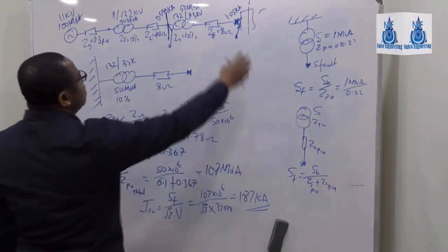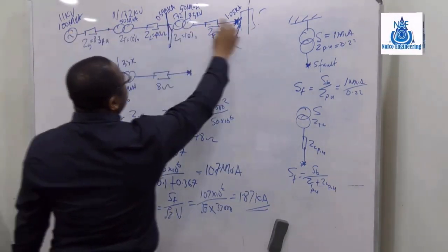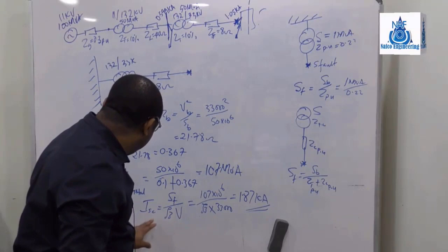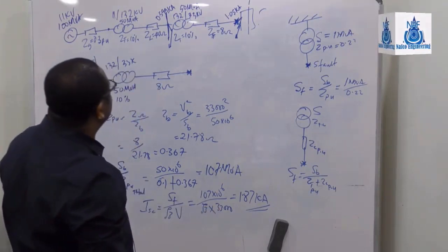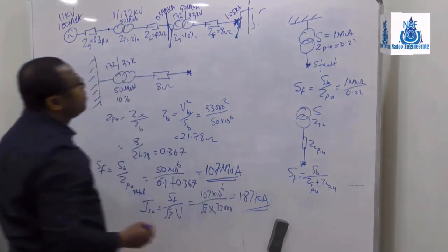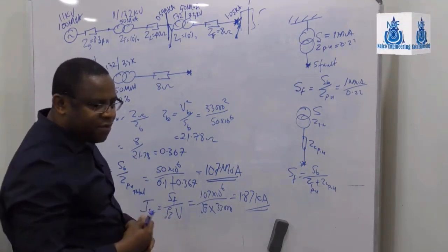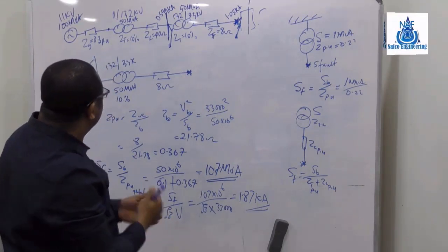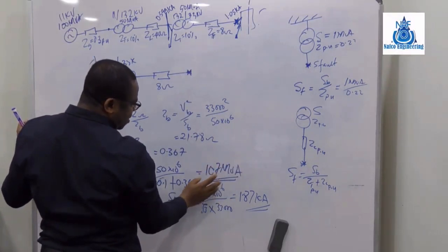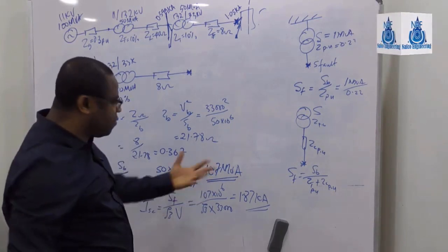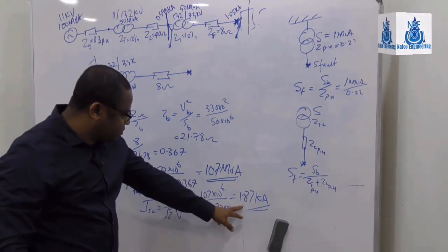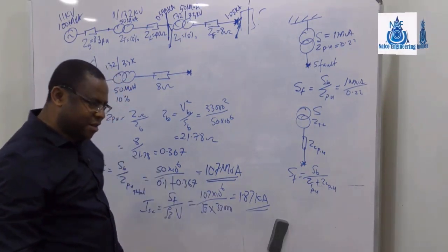So what I have here is 1.87 kilo amps. But if I check what I calculated from the whole of this, I got 1.05. So now I short circuit is 1.87, and the fault level is this. If I want to buy a switchgear for this, I'll just tell Actom or ABB that I need, let's say, a 110 MVA switchgear or a 2.5 kA rated switchgear.